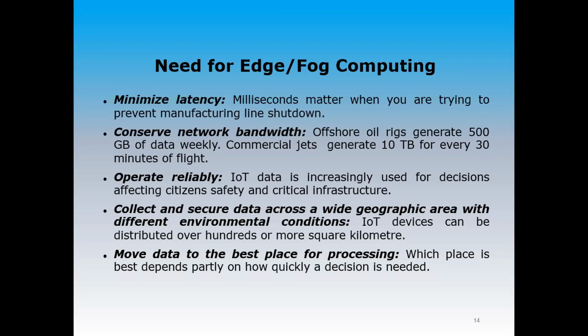And the analysis is going to be done in terms of how the power is delivered, how the health of the transformer is, the oil level, oil temperature, and those kinds of factors: power factor, voltage, what the level of voltage is, supply current, all kinds of things. Each time you keep sending the data, an analysis is happening at the cloud level, right? When you're doing the analysis, obviously you'll see the trend of the data, and if there is any kind of surge or anything, you have to take some action.